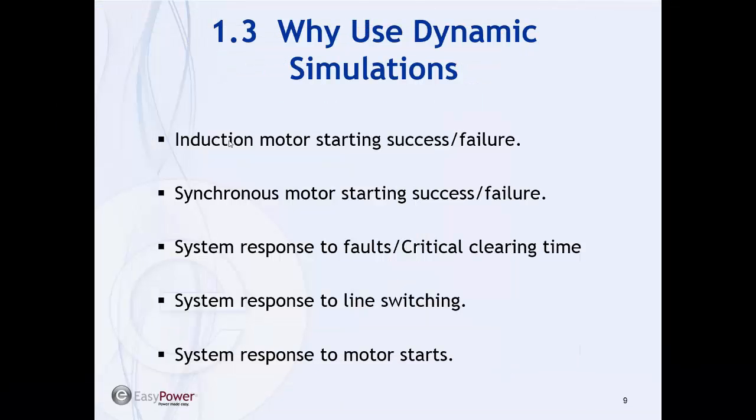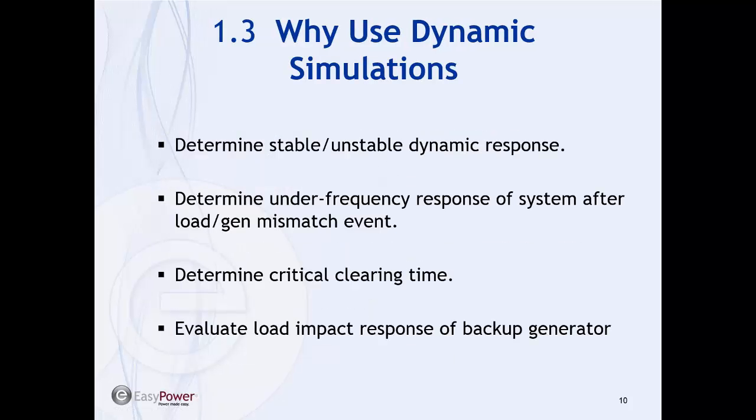Going back to the presentation, what we're trying to do is induction motor starting, success, failure, synchronous motor starting, success, failure, system response to faults, critical clearing time, system response to line switching, system response to motor start. If you see, there is one thing that all these events have in common, and that is the fact that they are transient. They happen at a certain time, you change them, you remove them, it's not something that stays there in your system.